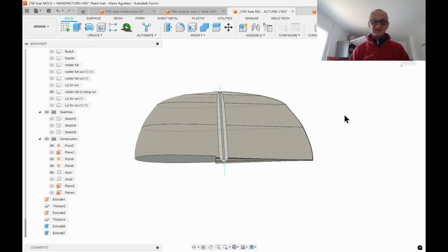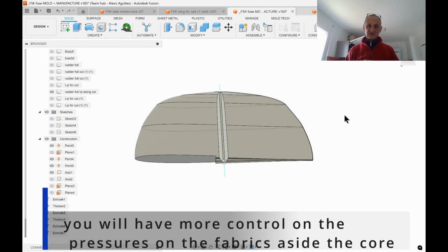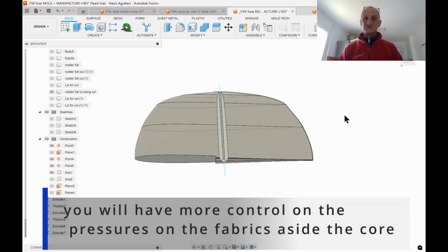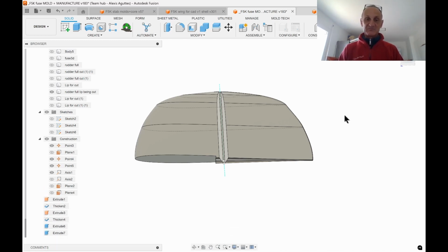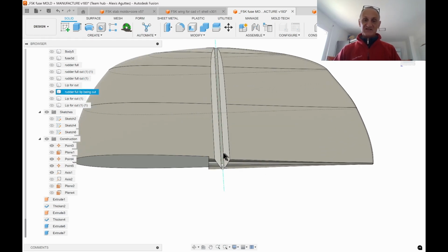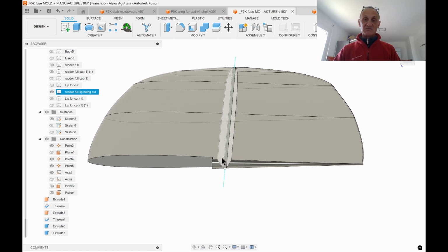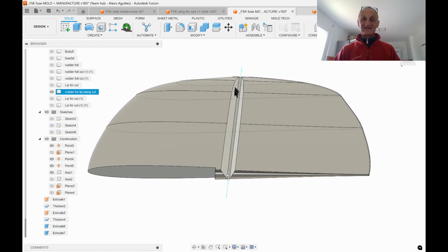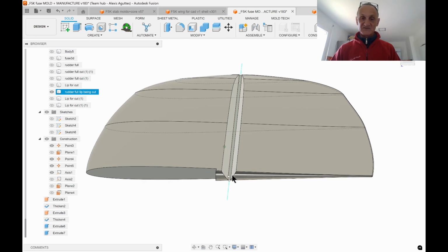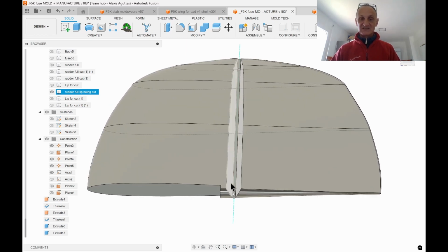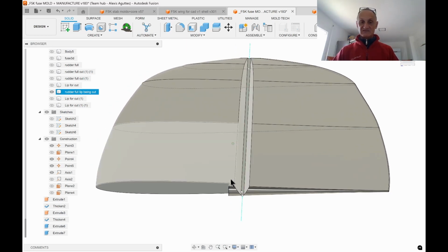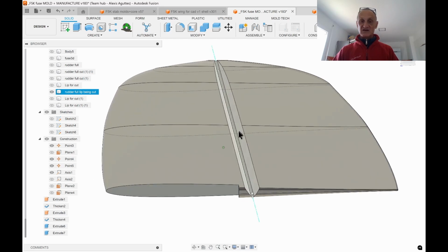So the second thing is that this lip will act as an insert. The composite walls insert are used. And this is exactly the place where an insert should be used to keep every corner, every angle with the carbon fabric strictly stuck to the core and to have something very, very neat. So I think that typically that's what this type of insert could achieve as a result.